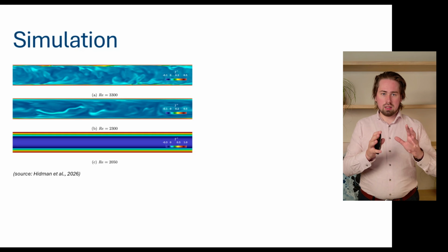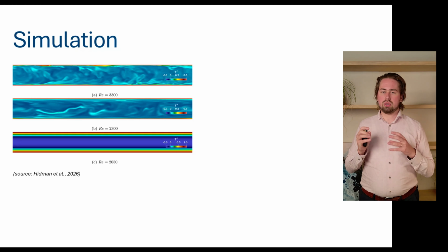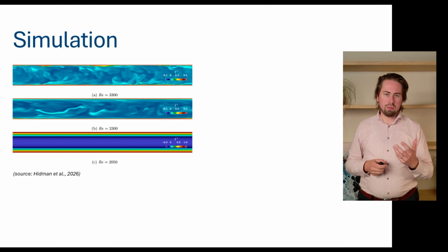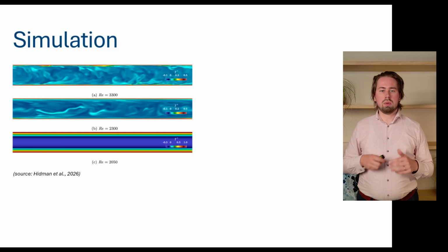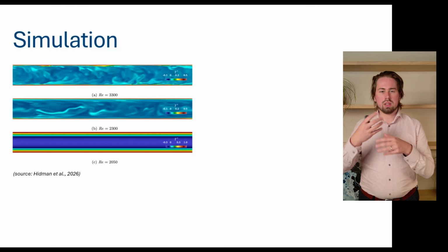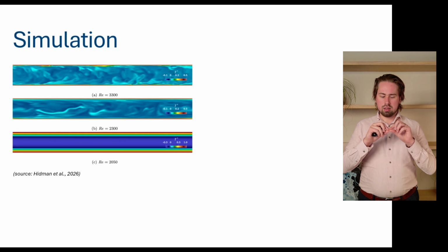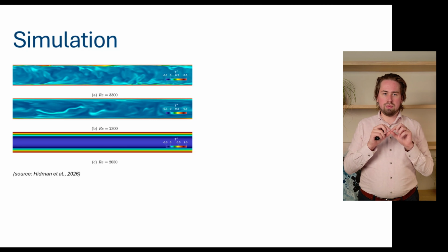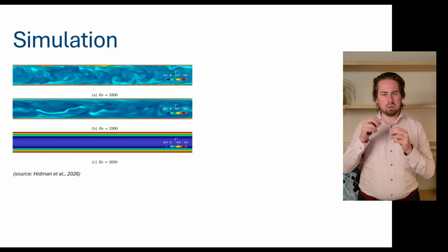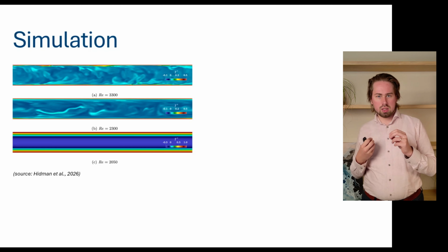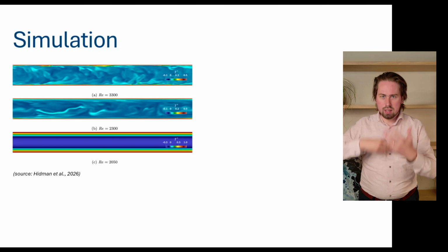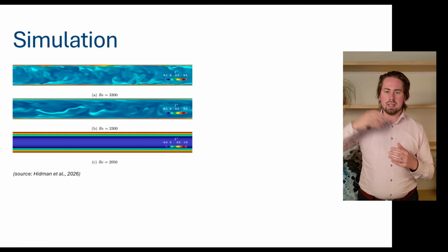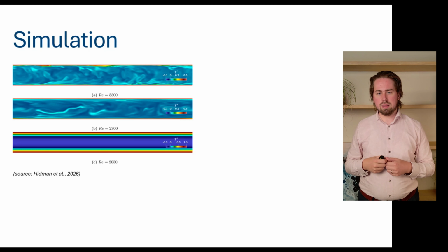Now, this is the result from the paper for the smooth probe. On top you have this very turbulent region, 3300, and you can see the fluid is beautifully mixed. You also see this turbulence happening, and at the pipe walls there is a very, very small boundary layer. You see a sharp gradient from this blue to this reddish color, but it's really small because in this turbulent region there is quite a lot of mixing and the heat gets mixed internally quite easily.